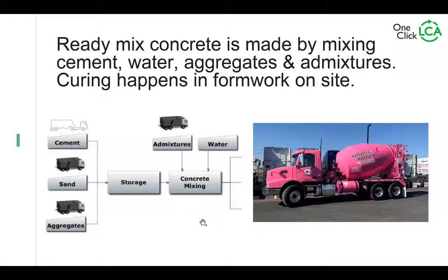And the curing will happen then in the formwork. Usually the strength is evaluated in 30 days, but you can of course set your strength evaluation time based on whatever design constraint you have. And the longer it is, the better chance you have using a high amount of alternative binders.